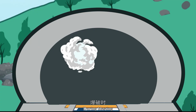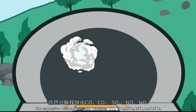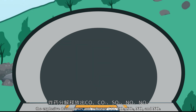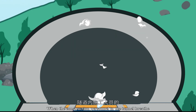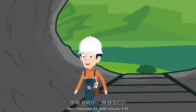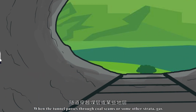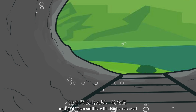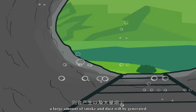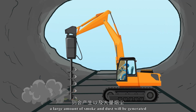During blasting, the explosive decomposes and releases CO, CO2, SO2, NO, and NO2. When the construction personnel in the tunnel breathe, they consume O2 and release CO2. When the tunnel passes through coal seams or some other strata, gas and hydrogen sulfide will also be released. During drilling and muck loading, a large amount of smoke and dust will be generated.